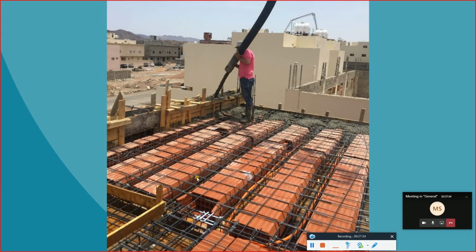So it will make our slabs lesser in weight. It means that the beams are going to carry less load. It means that the cross section of the beams is going to be lesser, the cross section of the columns is going to be lesser, and the cross section of the foundation is going to be lesser. And finally, the final estimate of the building is going to be lesser than the regular system. Although we do not have a lot of experienced people working with these slabs in Oman, they are starting already.